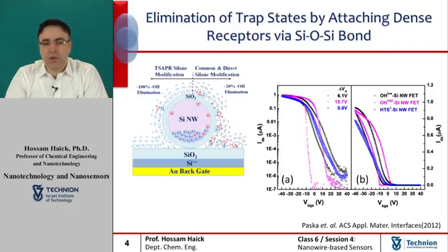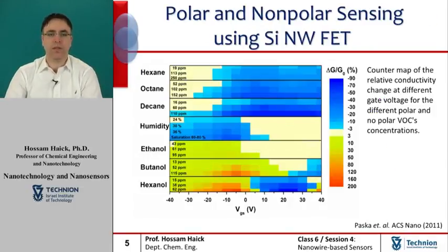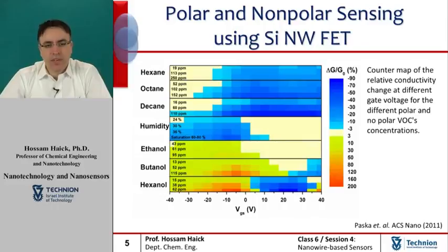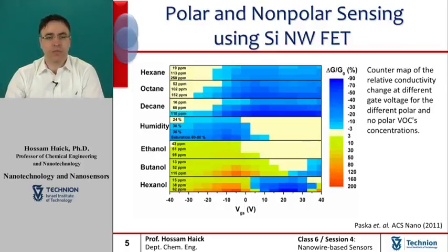The FET characteristics of the controlled assembly of hexyl trichlorosilane are reasonable and reproducible after 6 months, more or less, and have shown a change of around 5% drift only after this period. The passivation of the surface states and the elimination of the hysteresis effect with the help of advanced molecular layers can lead to improved sensing performance.